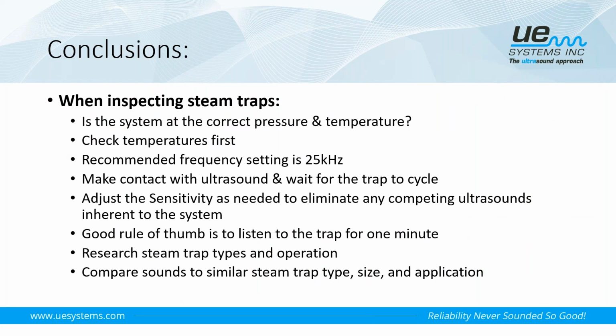So just wrapping up here, again, just some things to think about. When you're out initially, planning the survey, we want to take a look at the total steam system itself. Are we set, or are we at the correct pressure for the demand, for what it is that we're doing with the steam? Do we have the right temperatures? Again, we check with temperature first, whether that be your fancy infrared camera or just a simple spot radiometer.